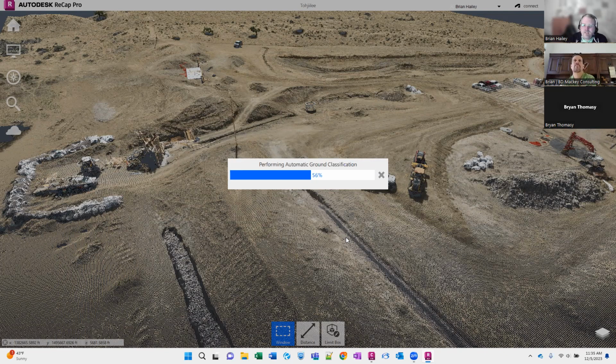Now, even after doing that, you're going to end up with a massive point cloud. Another new tool that's been added here is the ability to decimate your point cloud. Now, I know that sounds crazy. Oh, we're going to decimate, but when you're working in Civil 3D, you want to keep your surfaces under 1 million points. When you get up to 1 million points and larger, it starts writing out those silly MMS files, and it's just annoying, and everybody hates them, and there's really no need for a civil engineering project to have a surface with more than 1 million points. More than 100,000 points is probably pushing it, but I always try to limit my surfaces to about 900,000 points.